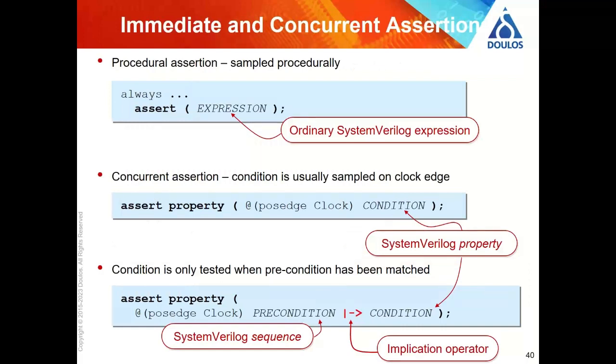Now, in terms of assertions, there are various ways of writing those. We could just use the assert statement inside a process. That's not what we'd use with property checking. That's just something that's true or false, and if it's false, then we can get it to stop the simulation, similar to the assert statement in VHDL.